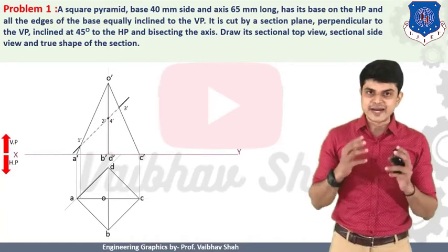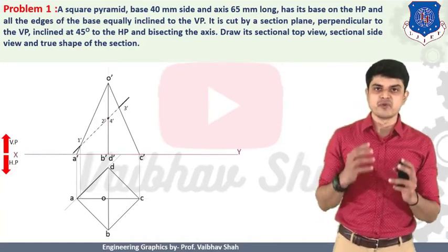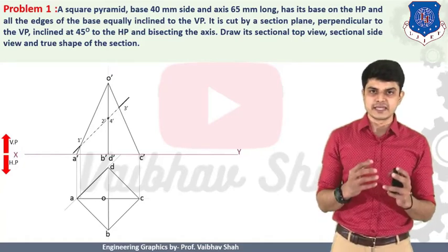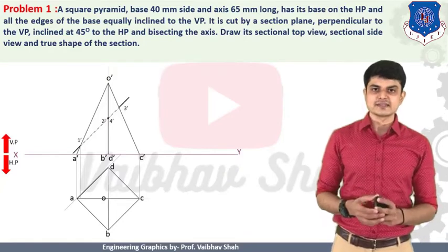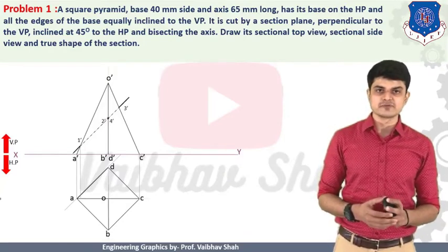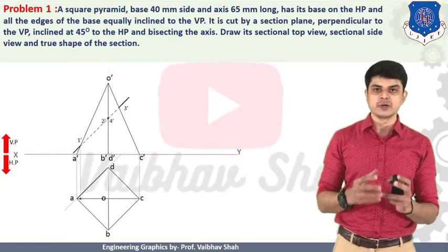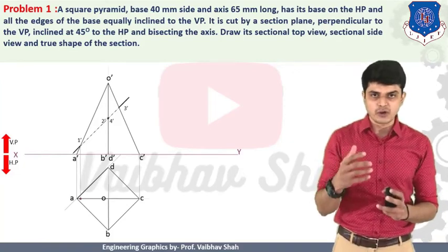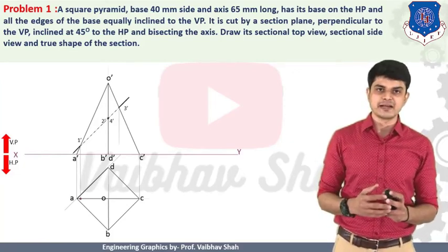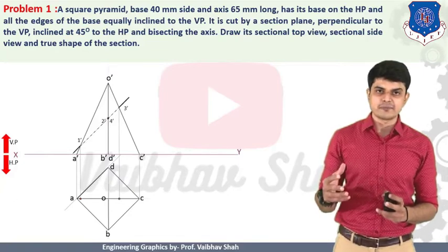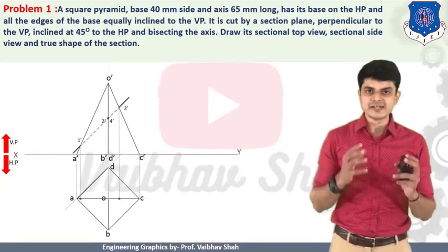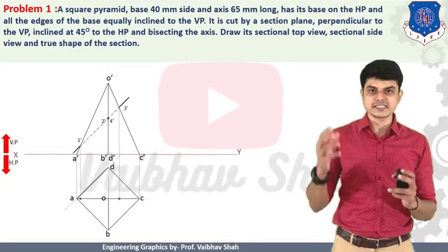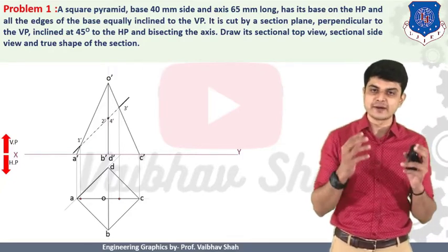So now let us draw a vertical line from your 1 dash point. It will cut the OA line somewhere on this top view. After getting this cutting, we should mark this point. This would be your point number 1 on your OA line. Thereafter we should draw a vertical line from your 3 dash point like this, and thereafter we should mark that point somewhere on the OC horizontal line. Now let us try to transfer the points 2 dash and 4 dash onto OB and OD respectively.